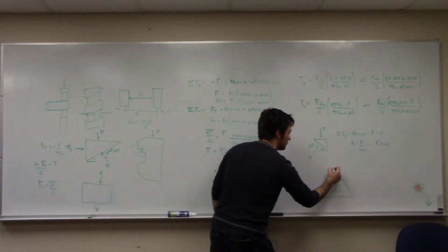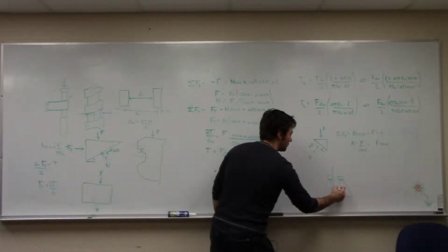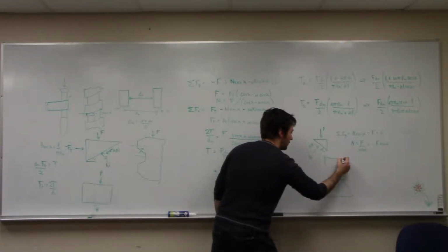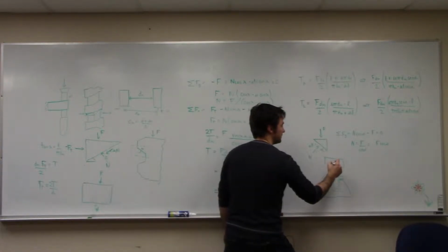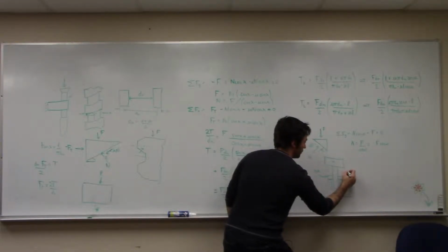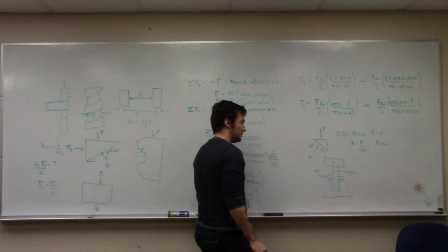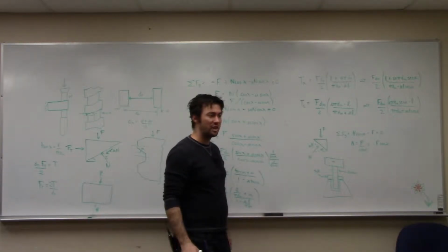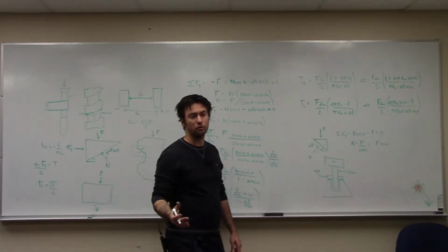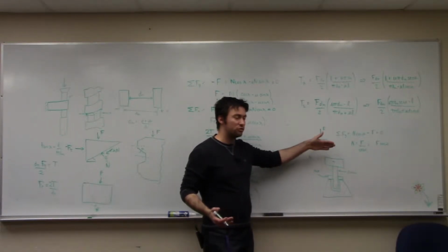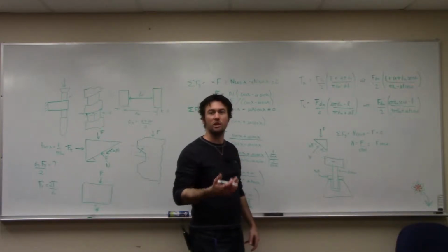And I'm going to put a screw through the nut. And I've got some sort of mass that I'm trying to lift up here. So here's a nut. Here's the screw. And the base, all that's doing is supporting the nut here. So the same equations that we have for turning the screw and leaving the nut fixed, they work just as well as if the screw is fixed against rotation and we rotate the nut.